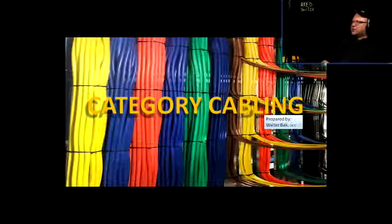Zip ties, all right? Thank you. That would be wrong. This is not a very good idea, because look here, you can actually see those cables being deformed. And once you deform the structure of the cable, you're altering the specifications of those cables. So there we go.